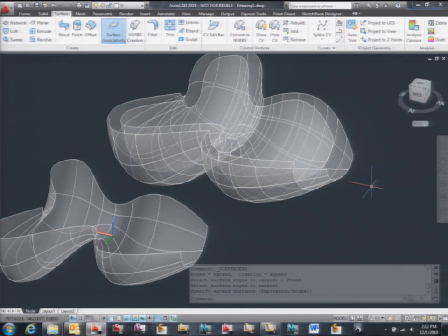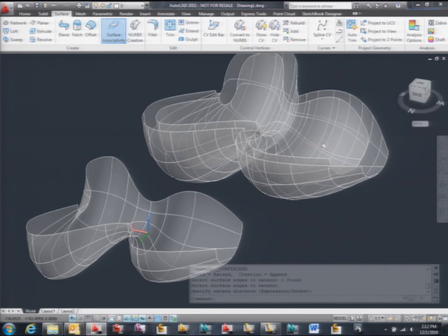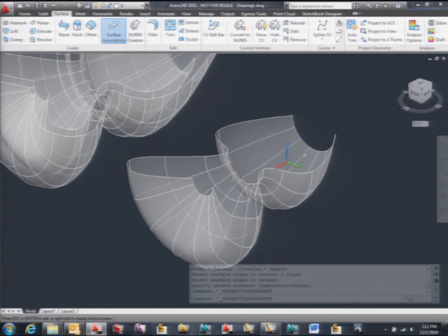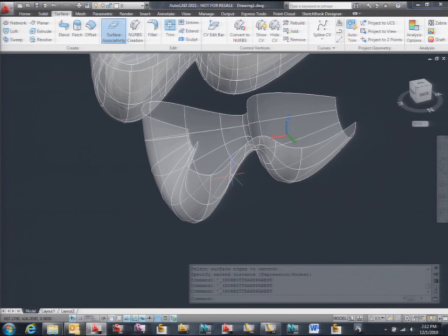Is there any kind of maximum or minimums on your offsets? No, so the offset will depend on what you're doing. For example, in the case of this surface, right? That's a great question, actually, because I'm going to show it on this one. So in this case, for example, the offset will create another surface that goes like this, right? At a certain point, if the distance is too big, it will self-intersect. At that stage, probably AutoCAD will tell you, you know what, I may pass and not let you do this. That's the forming constraint? Yeah.